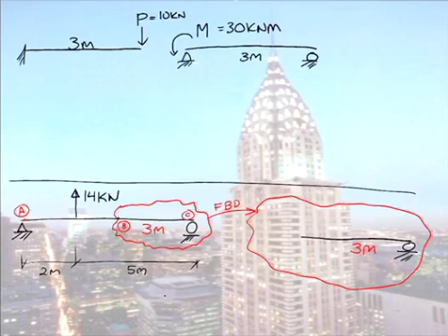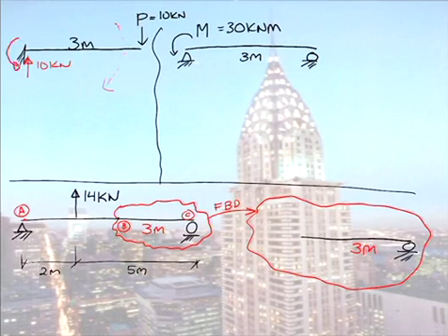So if we now move on to our beams. Let's look at this cantilever system first of all. I have 10 kilonewtons down here. So hopefully you could all work out we have a resisting 10 kilonewtons up. Is there any horizontal force on this system? No. So there'll be 0 horizontal force here. But these two forces, because they're not lined up, create a couple, and that 10 is causing a clockwise moment. So therefore, my reaction moment here would be equal to 10 times 3, which is 30.